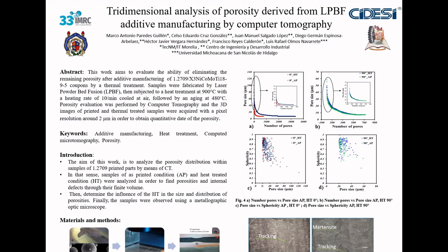However, porosity is one of the main challenges in the LPBF process and has a considerable impact upon fatigue profiles of a bulk. The porosity can usually be introduced by almost all AM process parameters. In order to prevent a failure, it is important to be able to determine the position, direction, shape, and size of the pores to know the final density of the piece that was printed.